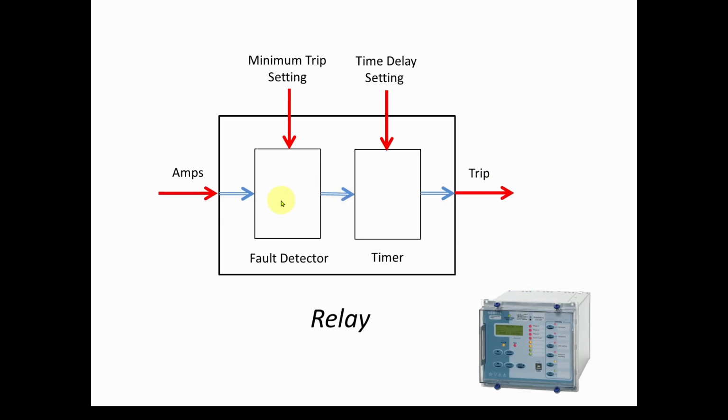Now, this is very similar to the way a fuse works. I did a video a while back explaining stuff that a lot of people don't understand about fuses. I encourage you to take a look at that because it will explain some of the details of how relays work and why they work that way. For example, you can see I've got a timer. A lot of people think that this time delay is always constant. In fact, for reasons that I explain in the fuse video, the time delay depends on how much current you've got.